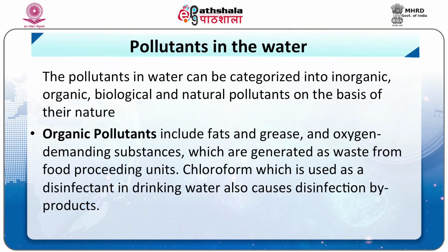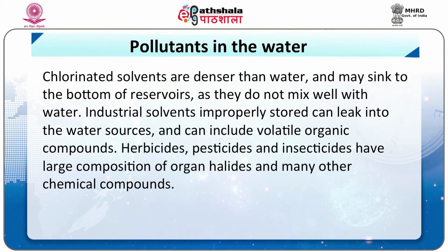Pollutants in water. Pollutants in water can be categorized into organic, inorganic, biological and natural pollutants on the basis of their nature. Organic pollutants include fats and grease and oxygen demanding substances, which are generated as waste from food processing units. Chloroform, which is used as a disinfectant in drinking water, can cause disinfection byproducts. Chlorinated solvents are denser than water and may sink to the bottom of reservoirs as they do not mix well with the water. Industrial solvents improperly stored can leak into water sources and can include volatile organic compounds.